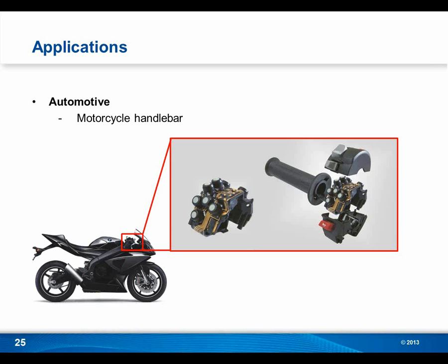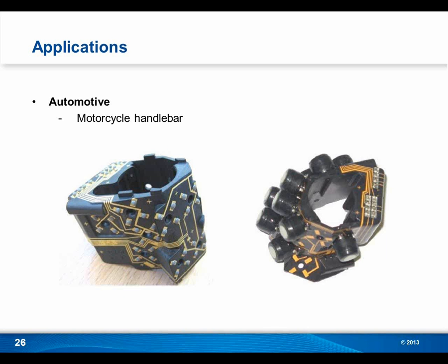Once again, we have the advantages of 3D design in a human-machine interface. So in this particular case, you're wrapping a number of buttons around a handlebar, and you're basically looking to control all these buttons with one thumb. And so you're using a lot of space. You're putting buttons in a place that is accessible in a difficult situation, basically just using one thumb, and using 3-dimensional SMT and putting solder placement and the parts in place. You get a very nice, simple, single part solution to the problem.